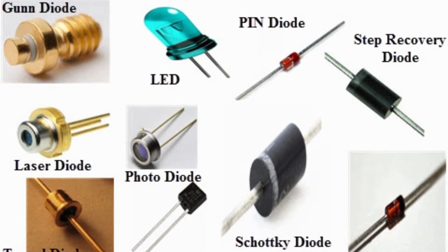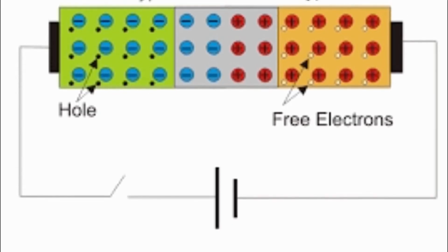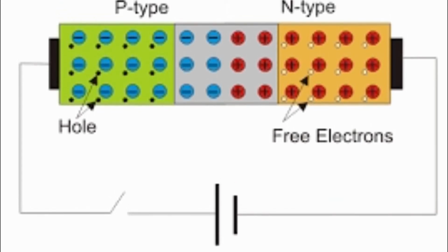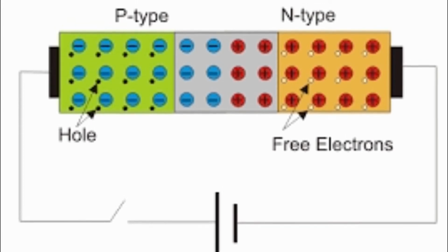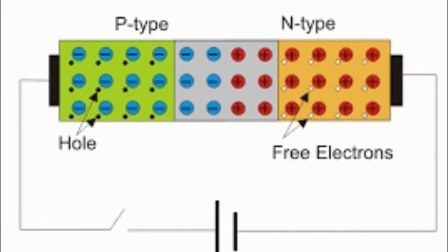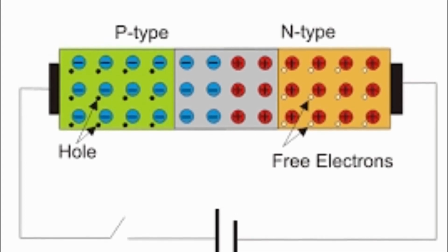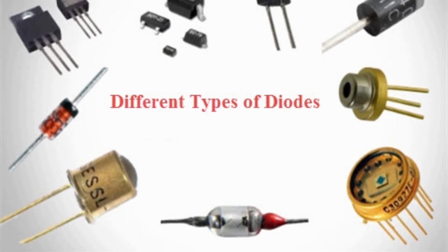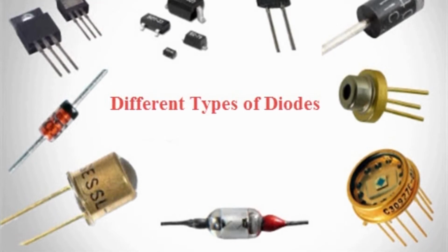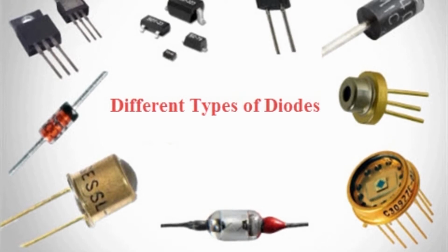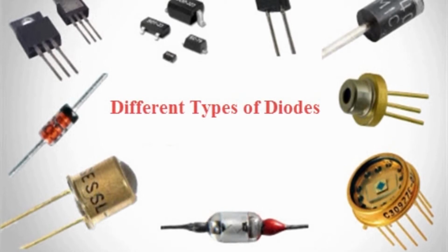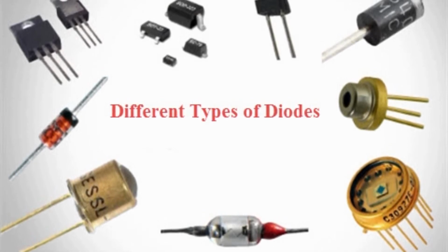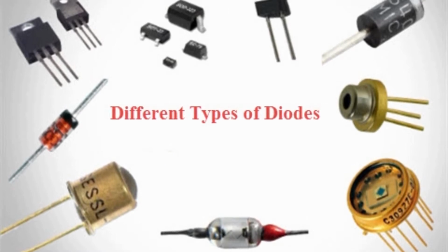Transient voltage suppression diodes: This diode is used to protect electronics that are sensitive against voltage spikes. Gold doped diodes: These diodes use gold as the dopant and can operate at signal frequencies even if the forward voltage drop increases. Super barrier diodes: These are also called rectifier diodes. These diodes have the property of low reverse leakage current as that of a normal PN junction diode and low forward voltage drop as that of a Schottky diode, with surge handling ability.